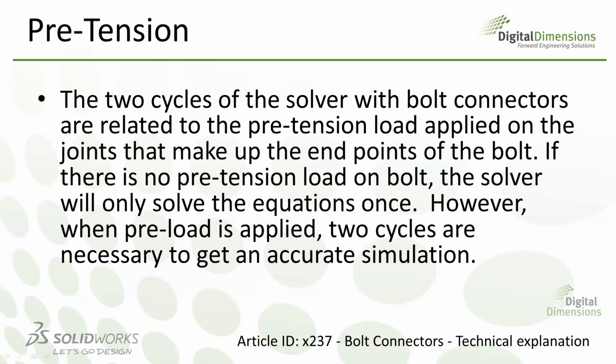To begin a review of these more unique features within the SOLIDWORKS bolt connectors, let's take a look at preload. Preload is also referred to as pretension. Pretension is denoted by the tension condition determined when adding a loading force to the bolt. When preload is defined in a bolt connector, it's important to note that a second cycle will occur within the solver to account for the load condition. This is why, when a zero preload condition has been defined, you receive this message explaining that a preload condition does not exist.